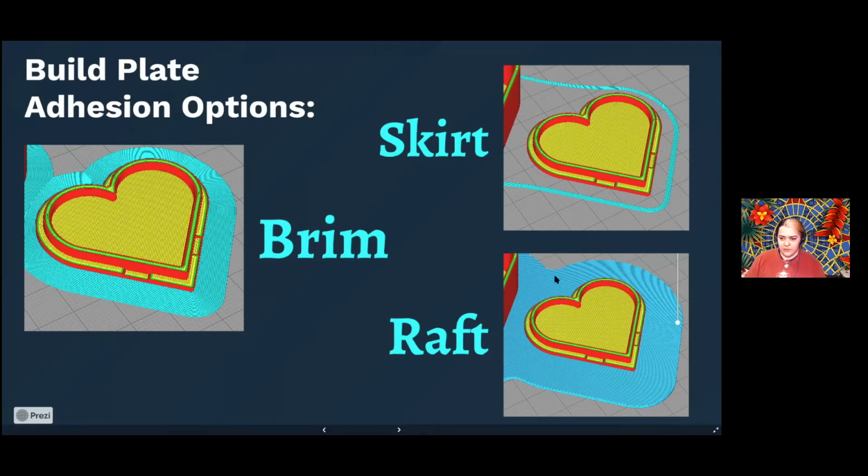And then as I was saying before about the type I don't like, this is the raft. It's like the brim, except it goes all the way under the model. It's like 3 or 4 layers of just solid plastic. And it makes sure your print prints, but if you've got pretty good adhesion, you really don't need this. This is really not necessary.